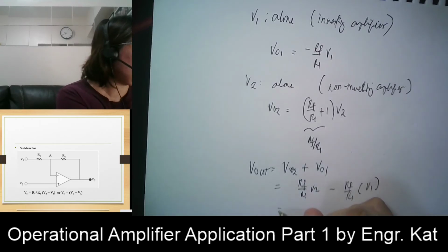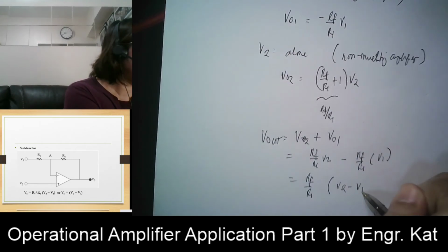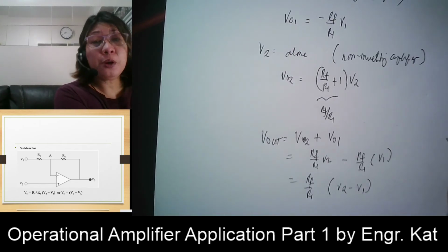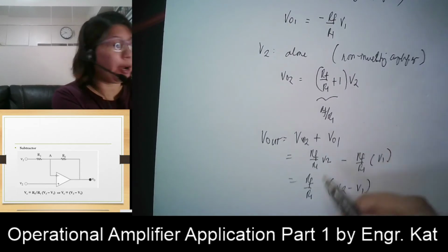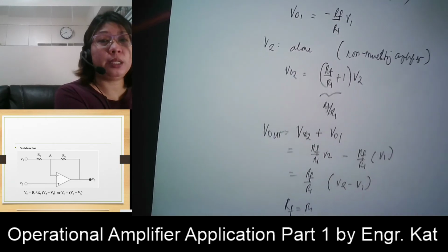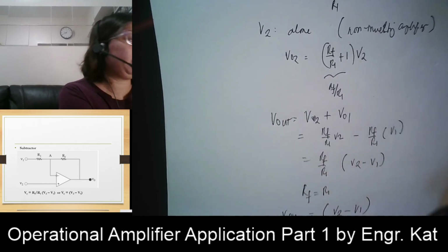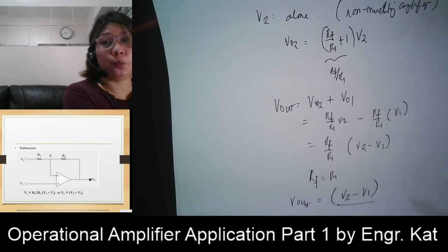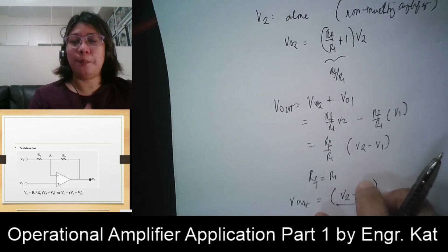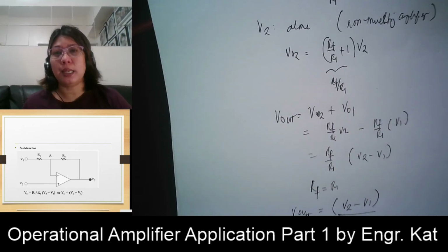Factoring out your RF all over R1, we have an answer which is equivalent to V2 minus V1. If we are going to simplify this further, and let us say RF will be equal to R1, we will be getting an output which is the difference between your two input voltages, V2 minus V1. So we have a subtractor. That is how your operational amplifier can be applied as a subtractor.